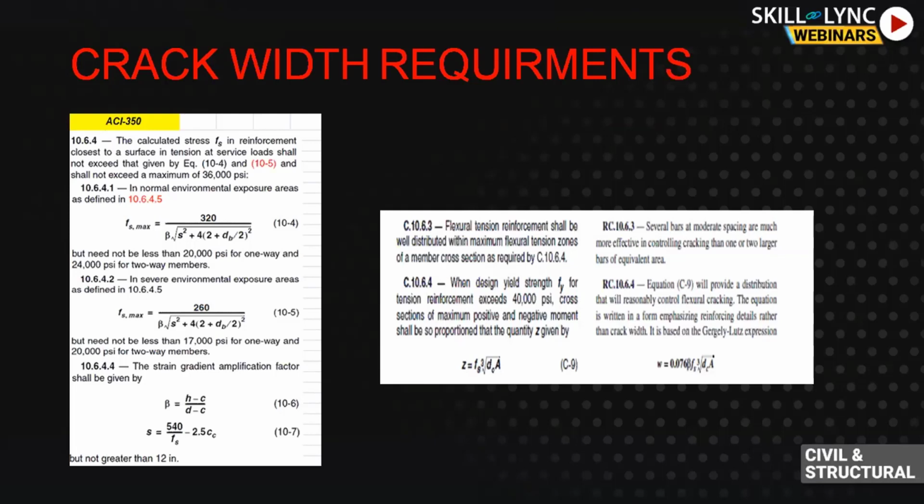People were using this till ACI 350-06 came. Now ACI 350-06 wants to limit severe exposure differently, and normal environmental exposure is different. And it is limiting two things. One is the allowable stress in your steel reinforcement.